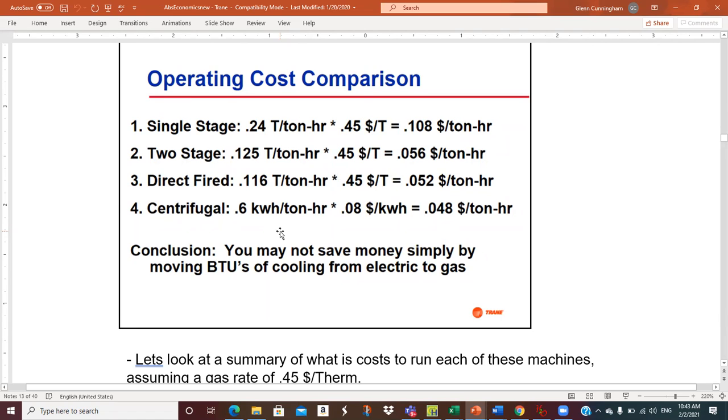So that's 2,047.8 BTUs. And so I'm going to get 12,000 BTUs of cooling for that. So 12,000 divided by 2,048, what it rounds to, is 5.86, between 5 and 6. So that COP on that centrifugal is pushing 6. Well, heck yeah, that's pretty darn efficient.